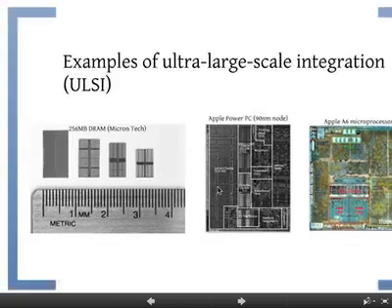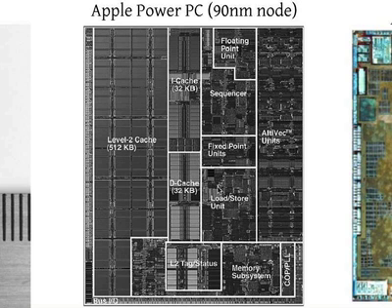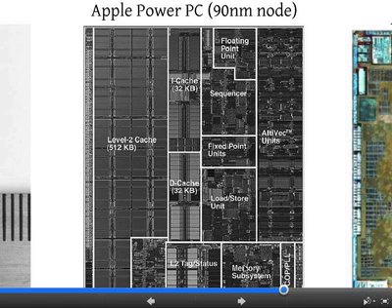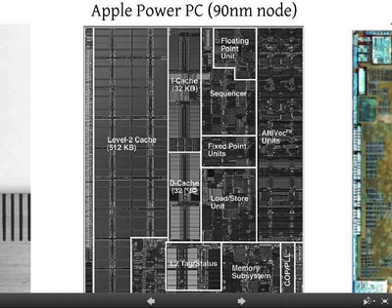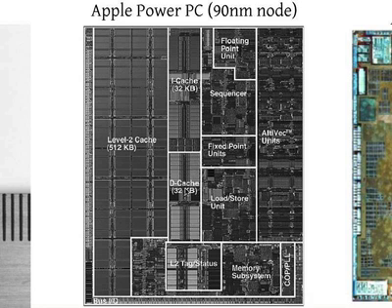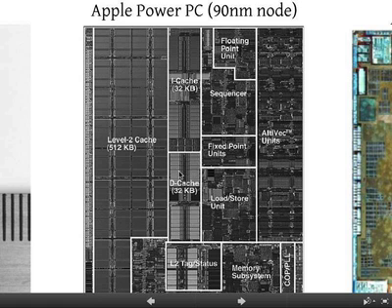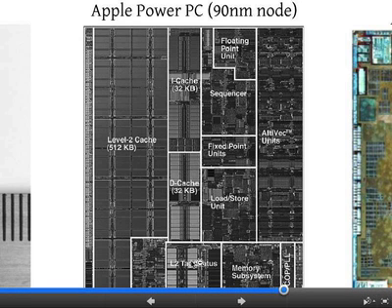Okay, let me zoom in. You can see the details here. So where's your CPU? Okay, there's a floating point unit where you do the digital calculations, fixed point units, memory subsystem. There's cache memory, which we just talked about. This is a single chip which included everything, right? Logic, memory, and level 2 cache. The cache which is closest to the CPU is called the level 1 cache, iCache, Dcache, all this kind of stuff. Anyway, that's what a Power PC from Apple looks like.